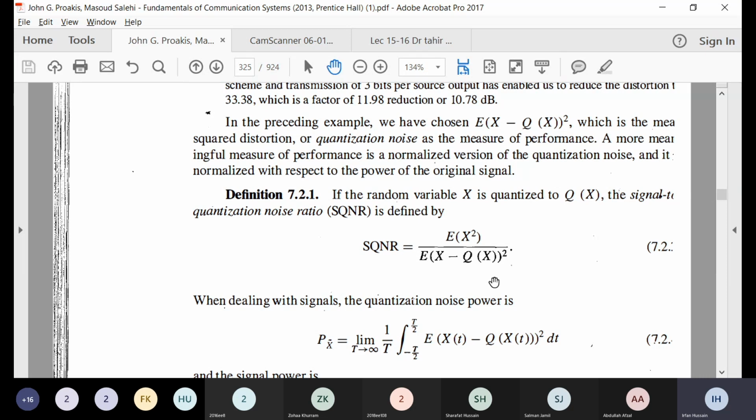So this will give me, this is not the actual noise. It is not the actual noise, which you added as rectified Gaussian noise or whatever channel effects there are. This is a quantization noise, a noise that has come about by the introduction of quantization. Right? So we just saw this earlier. This is its mean, same thing. This is the ratio of the signal power over the quantization noise power.